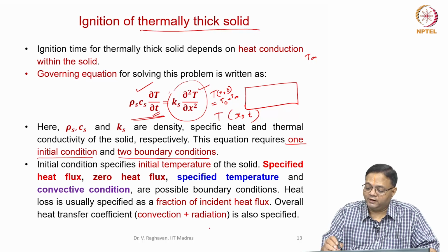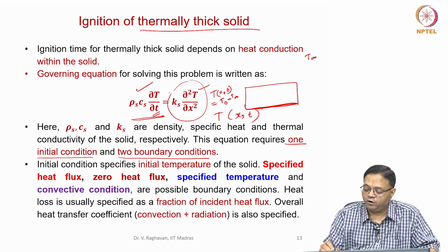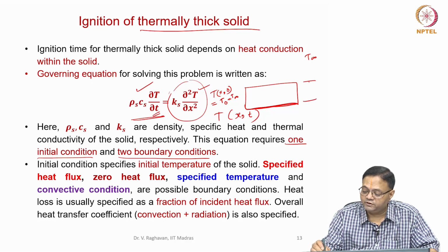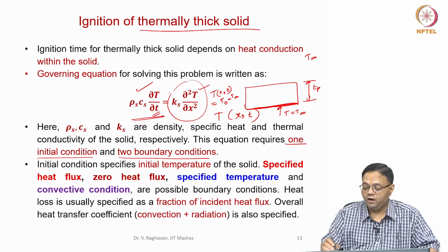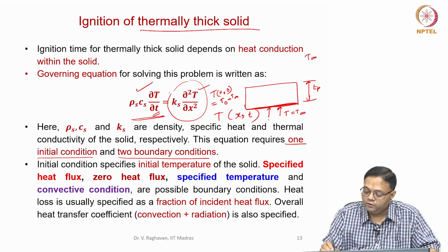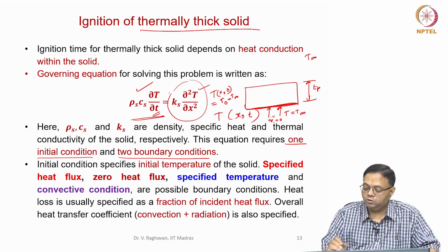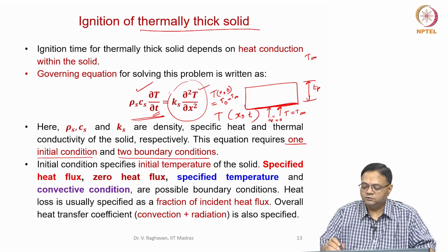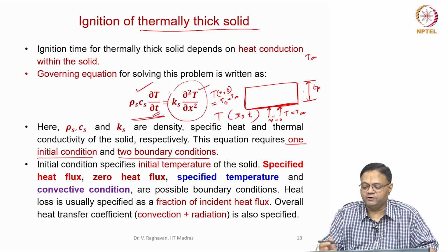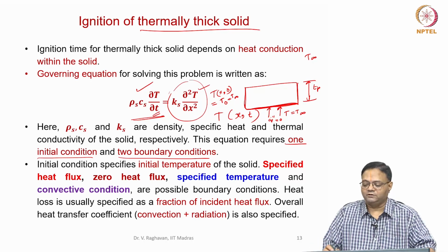Then, please understand that normally the bottom surface of the solid, at a physical thickness Tp here, I can have a Dirichlet condition, T equal to say T infinity, or I can say an insulated condition, q double dot equal to 0. Similarly, sides also I can give some convective condition or insulated, any condition based upon the problem I am trying to solve.